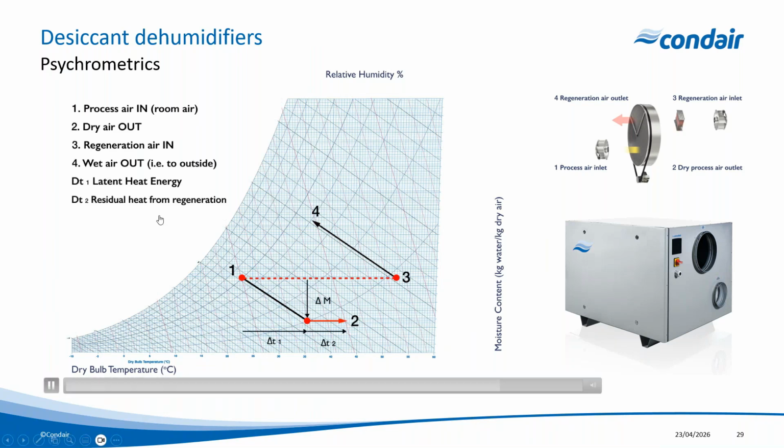Now, this also represents another challenge, because if we look at it psychrometrically and the customer wants 20 degrees C and 30% RH, we're going to be just here. And we know the process is going to be following the line of enthalpy. So we have to work backwards.